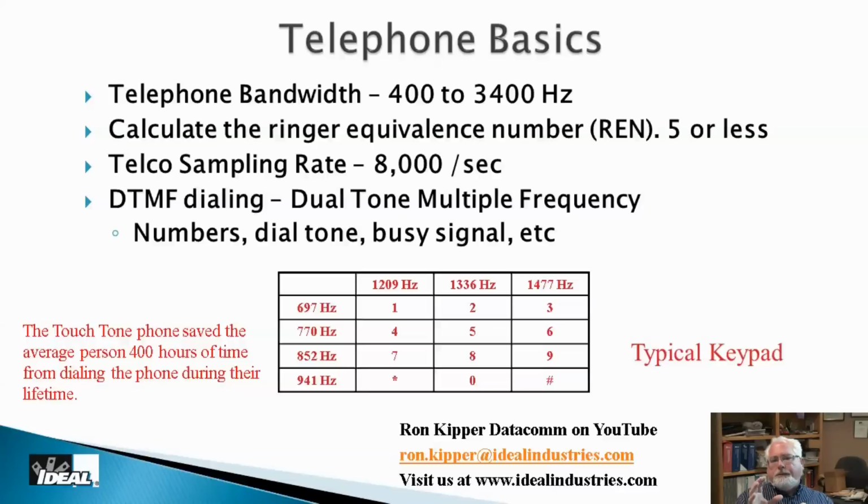Well, today the new digital type phones have a REN number that is dropping way down, like 0.2 today. So you might check with your local phone company and ask, hey, what's the max REN load you're allowing per household today? And let's say they come back and say 3. Well, if they said 3 and your phone is a 0.2, 0.2 goes into 3 actually 15 times. And technically 15 phones could be used in that building. And again, we should be able to talk to Grandma technically.